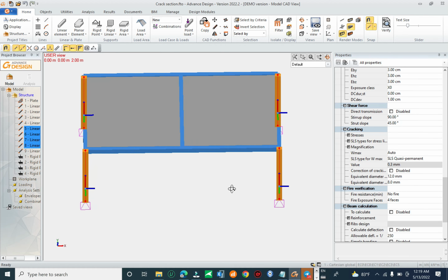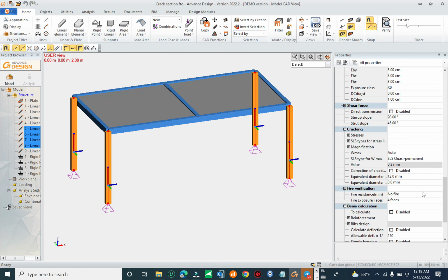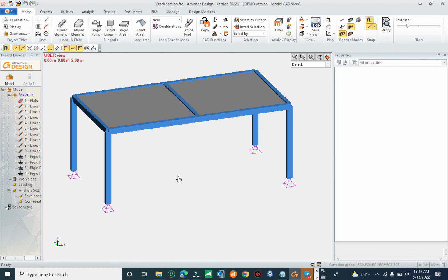After you input for Graitec and you run the P-delta analysis, include large displacement, imperfection, global imperfection, local imperfection, and notional load. And for concrete, we have to consider the property for the long term. It affects our structure.